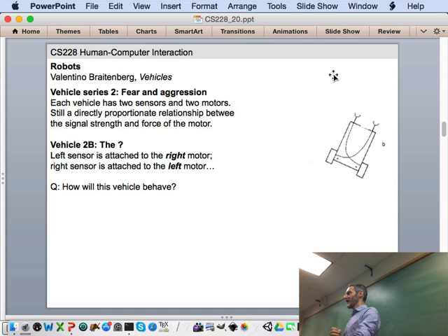The light signal increases and it speeds up, right? So it starts to accelerate the turn. And as it's accelerating the turn, both sensors are starting to fire more strongly, so both wheels are starting to turn faster. How does this end? With it chasing the light, right? If it's a naked bulb down within reach of the robot, it will smash into it